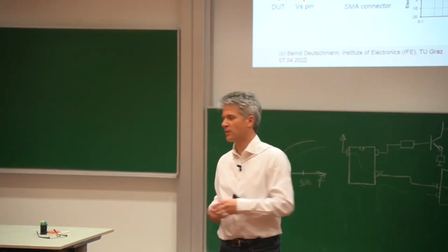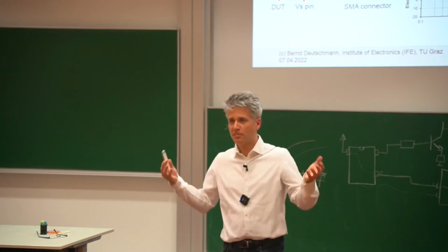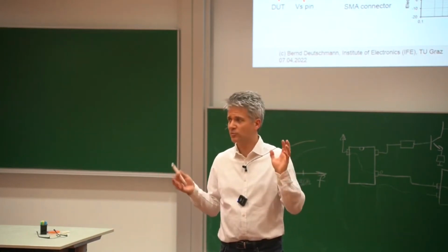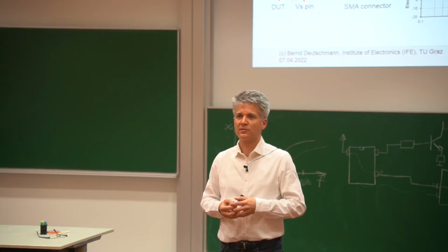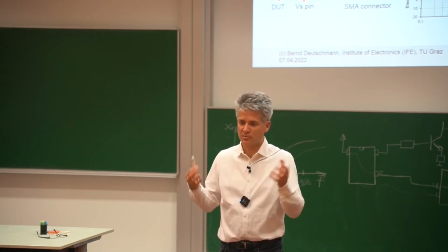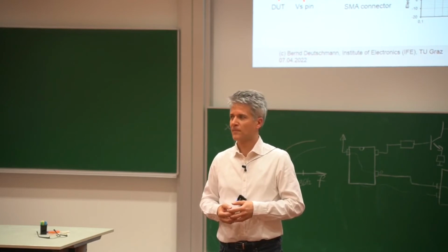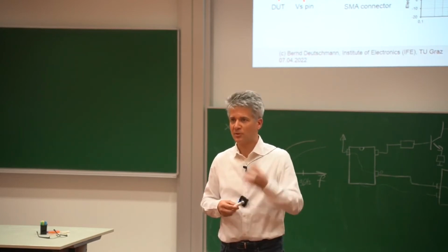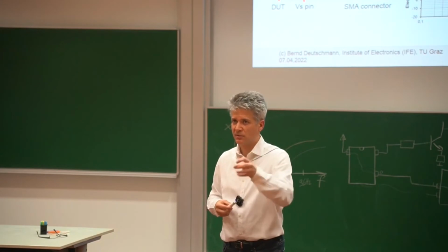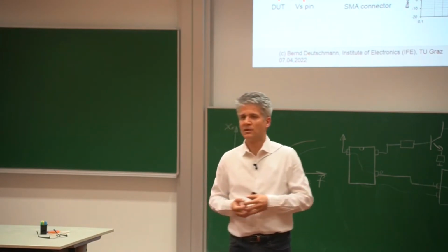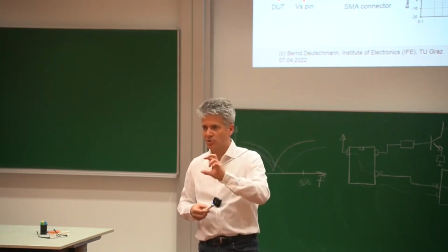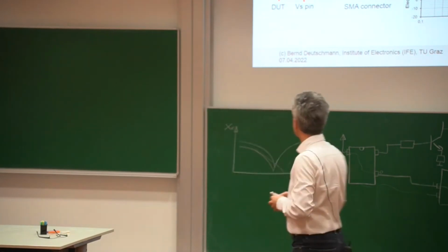And the mobility of the electrons is at least factor 2 to 3 higher. So therefore, we have, for example, smaller feature sizes, smaller R-on resistances. And the R-on is very important because we are dissipating heat on the internal resistance of the switch, and especially when we are changing the switch from high to low and low to high.